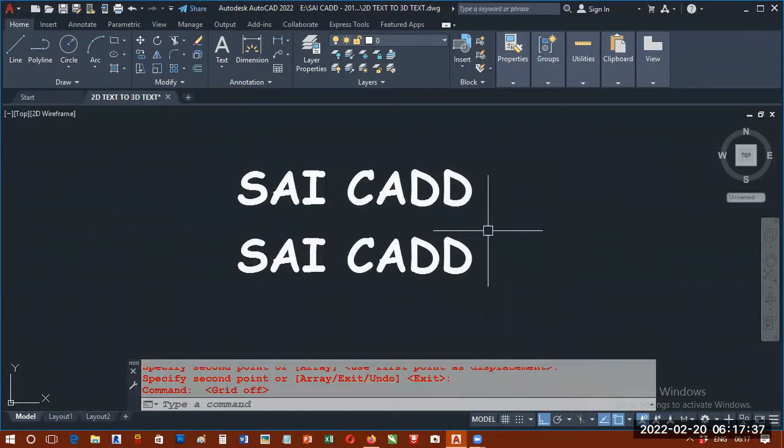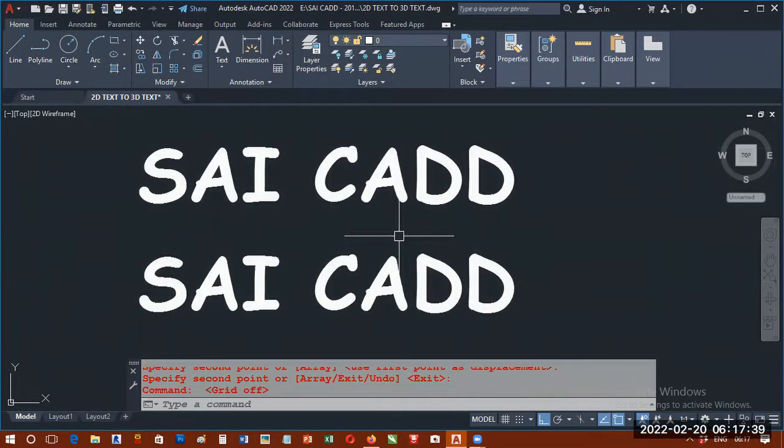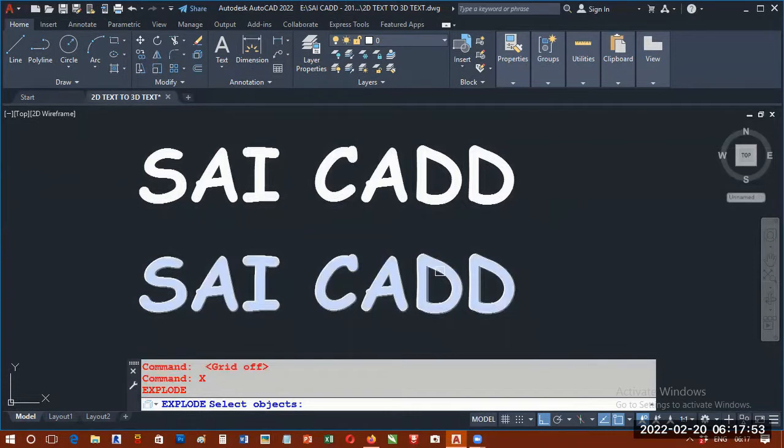Now, you know that in AutoCAD we normally cannot explode the text. Let us try that out. X, enter. Explode command short form is X, enter. Select this text. Once I click on that, in the command prompt you can notice this red color line here. I was not able to explode it. So in this method, we cannot explode the text.